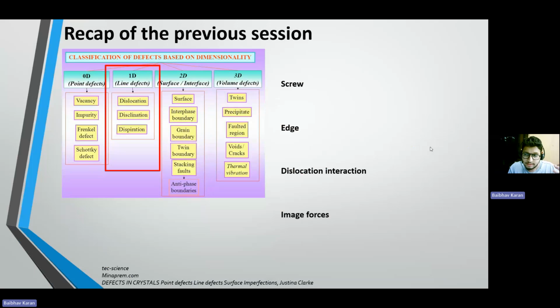So, when we consider the presence of defects such as dislocations in the material, the yield strength which we are observing is decreased because of that. That's why the theoretical strength is not valid, because of the presence of defects in the material. So when we are going to the nanoscale region, the material will be defect free because of these image forces. What does that mean? If the material is defect free, the strength will be extremely high.